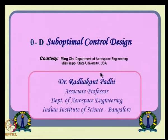The whole concept of theta-D control design tries to address one issue of SDRE, that online solution of the Riccati equation is problematic. If the dimension gets bigger and bigger, online solution of the Riccati equation is a concern. You cannot really do that online. So how do you circumvent that? How do you propose a different technique which will address roughly the same or similar problems, but will not have that difficulty?